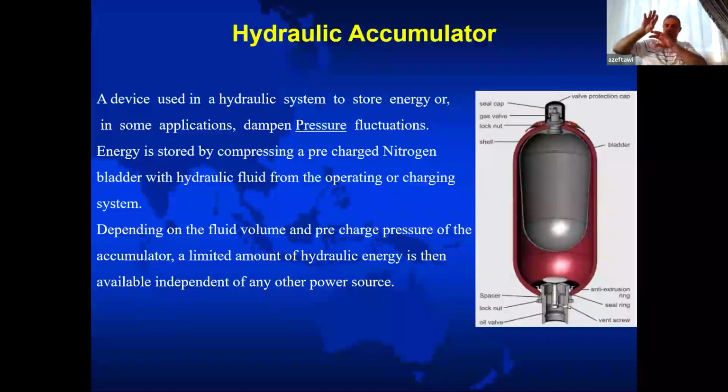So equilibrium is there. But if you lost the power, then the hydraulic pressure will go down, creating differential pressure. This allows the nitrogen to expand, this rubber element, which is the bladder. So instead of filling a quarter of the cylinder, it might fill 90% of the cylinder, pushing this hydraulic oil into the hydraulic hoses that go to the emergency devices, which is pressure control equipment.